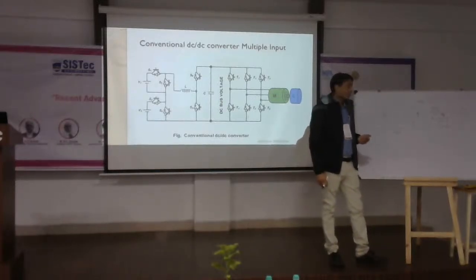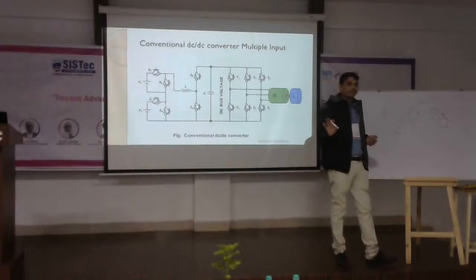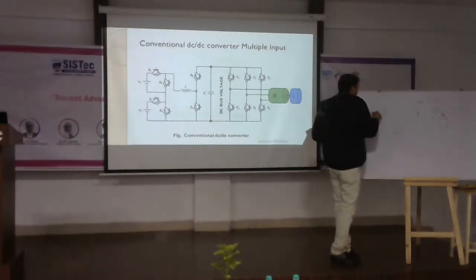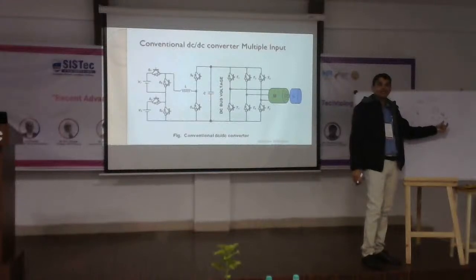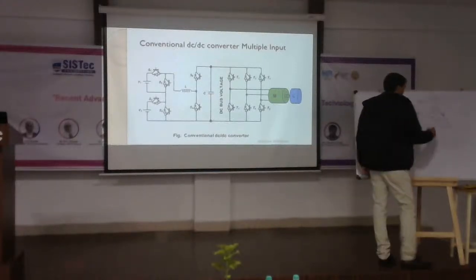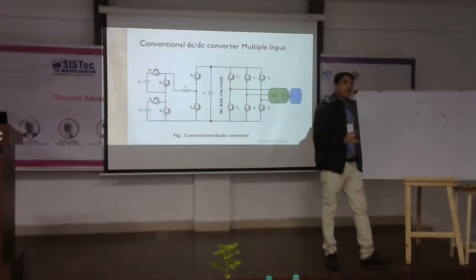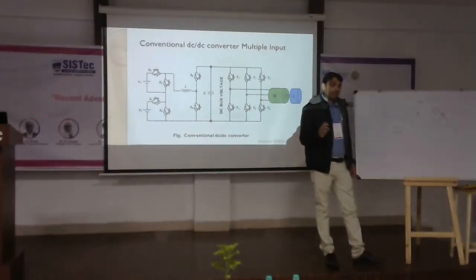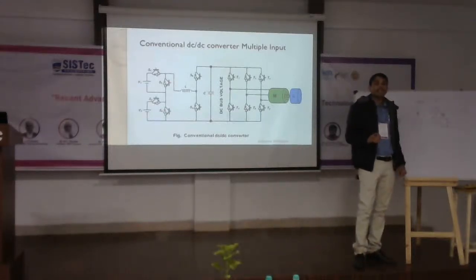Getting my point? So what will happen? How much voltage are we getting? Suppose the input voltage magnitude is 10 volts, I am taking it as an example, with 50% on and 50% off. What will the average voltage be? That is 5 volts, because for the 50% turn-on time the magnitude was 10 volts only, and for the remaining 50% the voltage is 0.